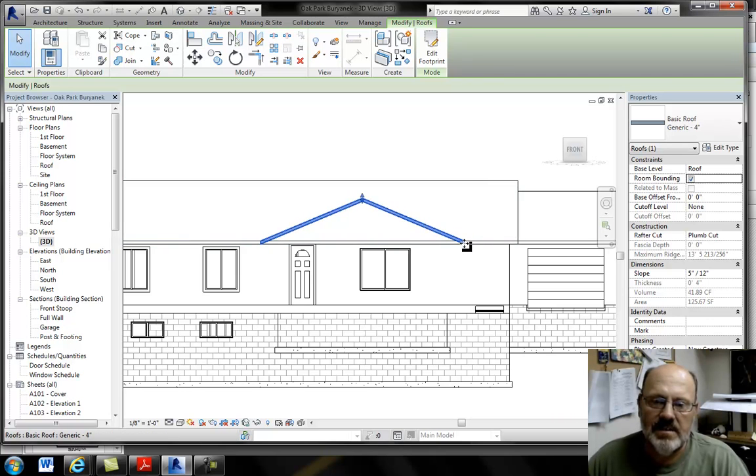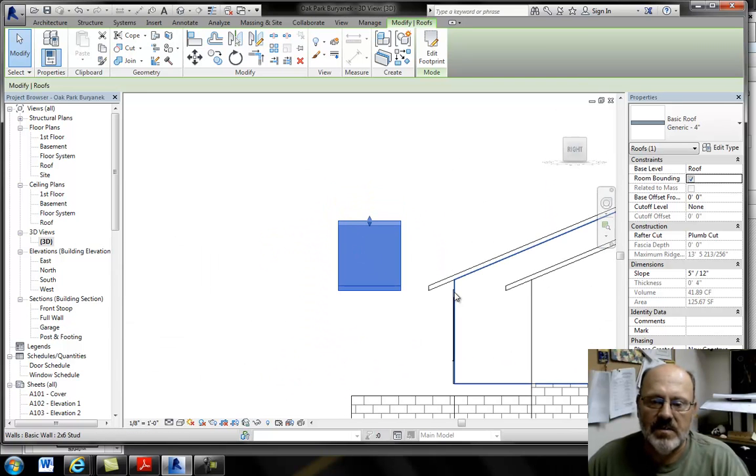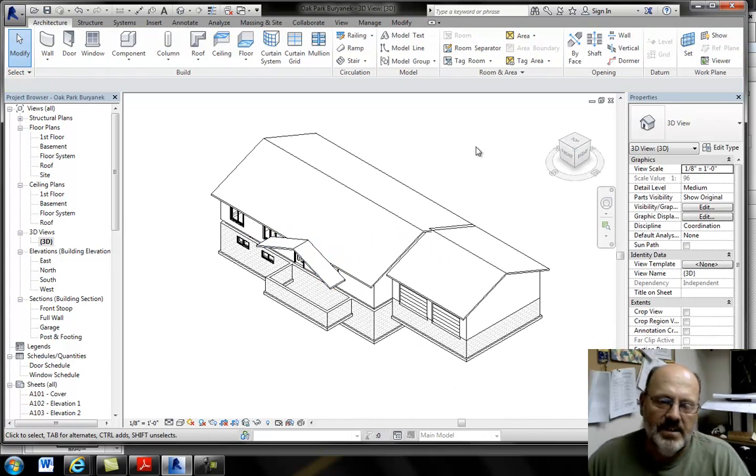It did not give me this offset. And so if this is 2 feet, if I go over a foot and down 5, over a foot and down 5, I'm 10 inches lower. So out at this edge, I'm 10 inches lower. So that's why I had to put the minus 10 inches in there. Funny looking little roof sitting out there.